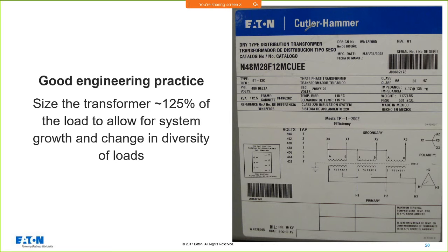So one of the things you have to remember when you do your load calculations, and I know there are a lot of people that say that the load calculations in 220 are inflated because of the lighting loads, because of the square foot calculations, etc. But you can't just count on whether you feel that's inflated.